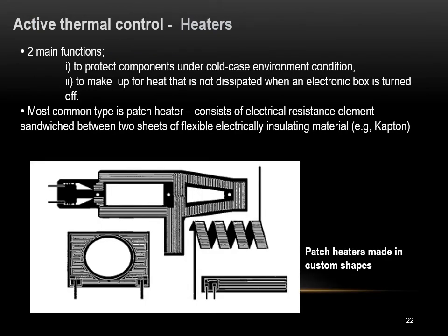An example of active thermal control is the heater. The heater is the simplest and most obvious active thermal control device. Heaters may be in the form of compact metal-mounted resistors, metal coaxial cable in which the heating element forms the core of the cable, or adhesive sheet.